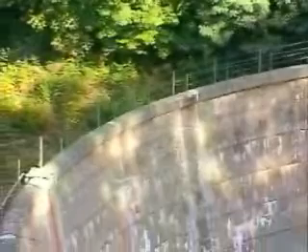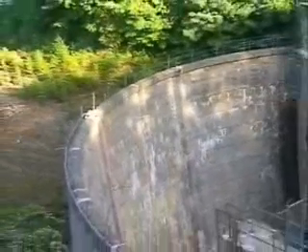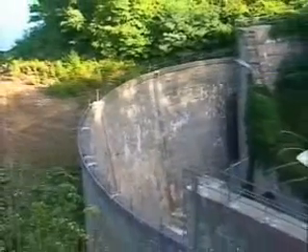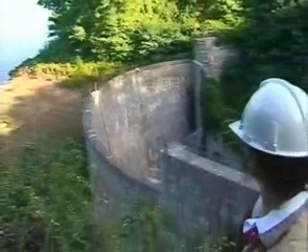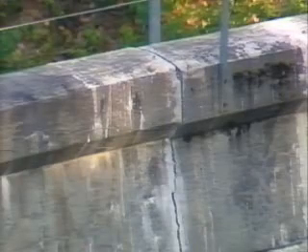Finding displacement by sighting along the crest of an arch dam is difficult because of the curvature. So at arch dams, study the crest from high on an abutment if possible. Also, look carefully at joints for offsets. And look at the concrete around handrails and other embedded metalwork for cracking that indicates displacement may be occurring.